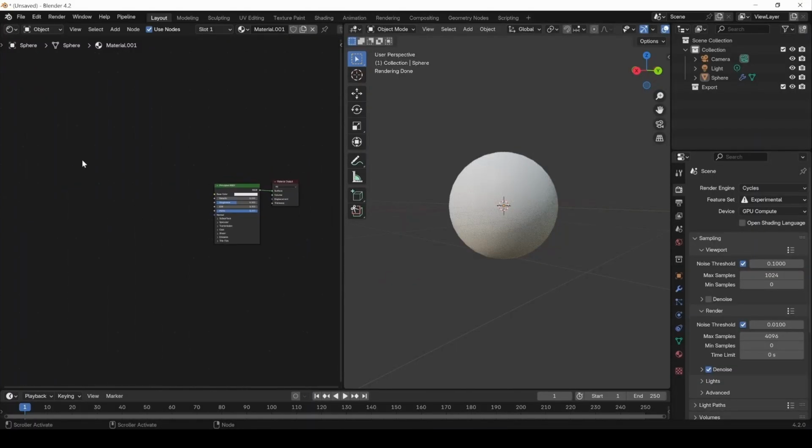You can start adding them one by one: take the image texture of the base color and link it to the base color, then get metallic and link it to metallic, get roughness and link it to roughness, get normals, add a normal map node with it and link it to normal, and then select them all, press Ctrl T on one to get the mapping, and just link it to all of them. This is a way to do it, but actually let me show you another way to do it.